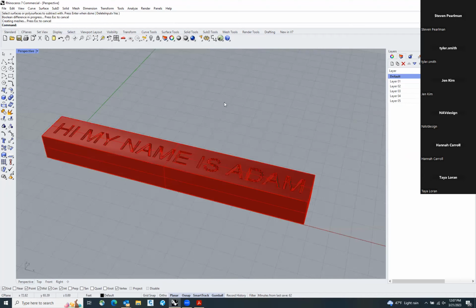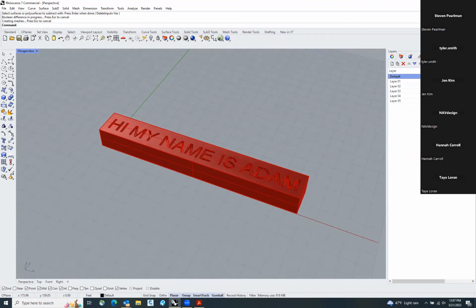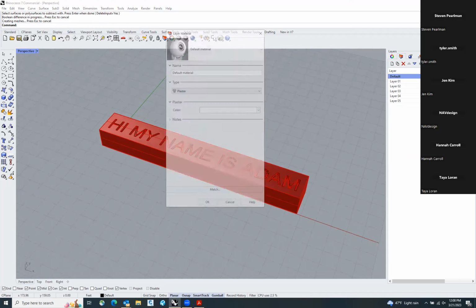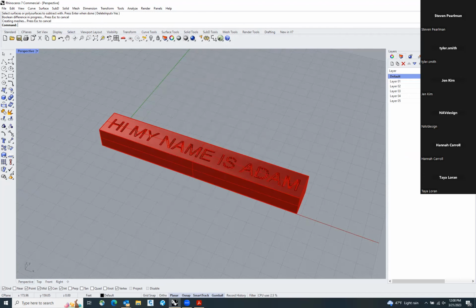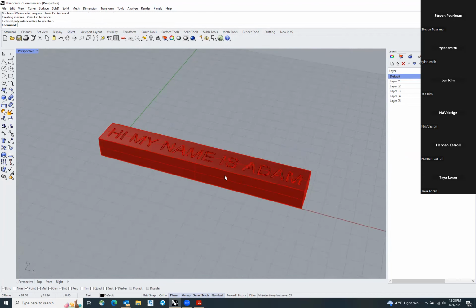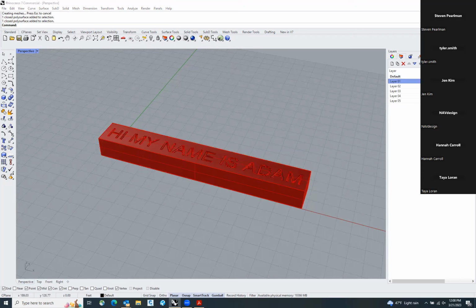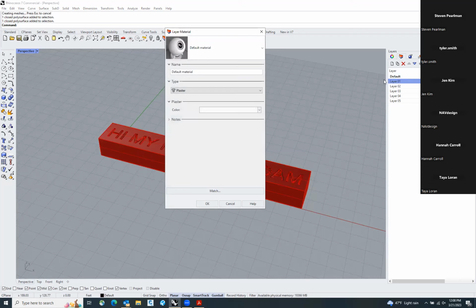I'm going to double click into this window here to go over some materials. Rhino is great because you can actually do some rendering in the model, so you don't have to take it to Lumion or Enscape. You can get a quick representation through Rhino's rendering software. I'm going to click materials, which are generically assigned by layer.